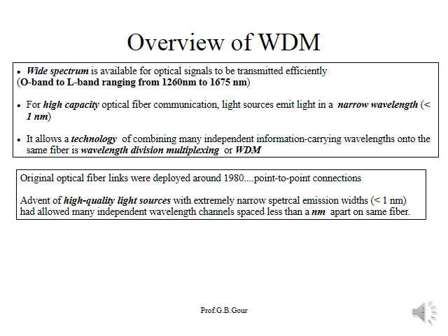Let us see in the next slide the concept of wavelength division multiplexing. Normally you will get a question like: define WDM and explain briefly, for 3 to 4 or maybe a maximum of 5 marks. So how can we define it? It is a concept or technology of combining more than one independent wavelength, where each wavelength is uniquely different and carries differently formatted data.